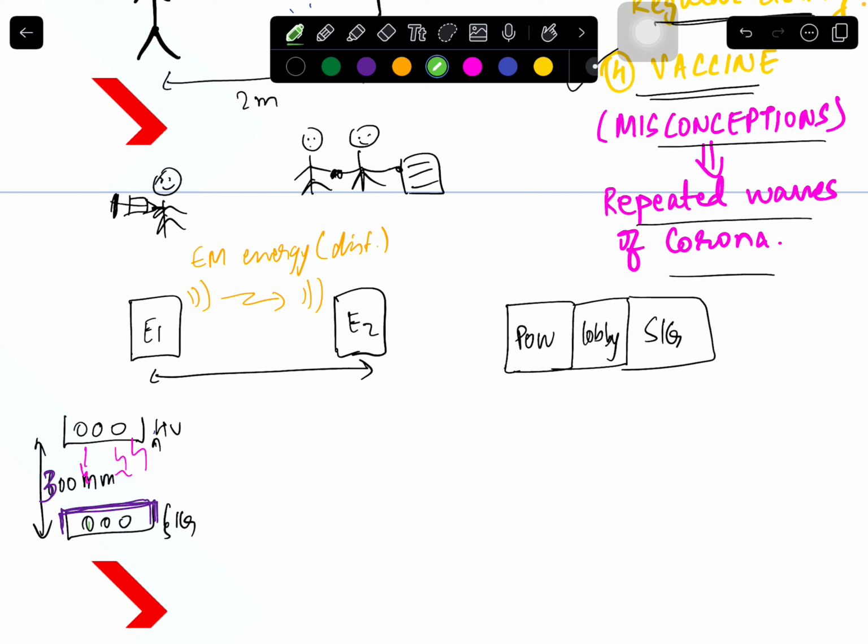Also shield your cables and connect it to earth. So use shielded cables and bond it to earth on both sides. About earthing both sides or bonding both sides of the cable shield, or single side bonding, in DC traction what we do, AC traction what we do, whether stray current can flow or not. All those things we'll be covering in a different video, but right now we are just giving a basic understanding.